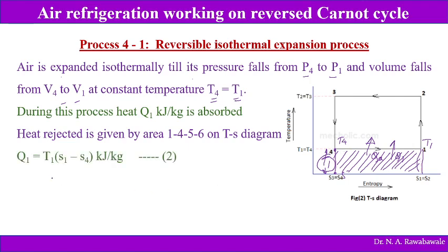So Q1 is T1 times S1 minus S4: the height of this rectangle is T1 and S1 minus S4 is its width. This gives us the amount of heat energy absorbed.